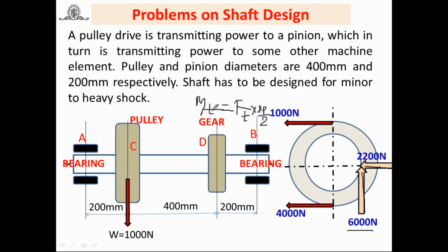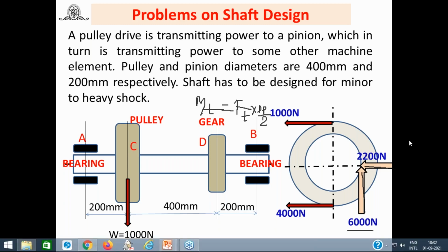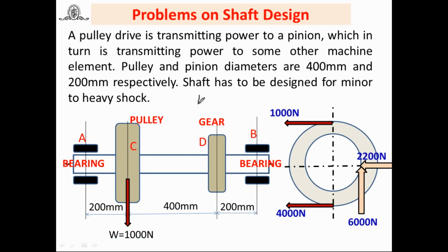Remember this thing. And similarly for a pulley, what is the torque? T1 minus T2 into the radius of the pulley. What you will get is the torque, because T1 and T2 are also forces, and force into this radius is nothing but a moment, that is torque. Remember these things. This formula we have to use. I hope you got it.